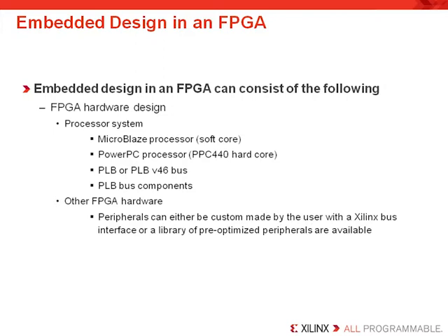Typical embedded systems are tuned for low cost, minimal power consumption, relative speed, and minimal FPGA resource utilization. As you may know, many customers like to store their software code inside of the FPGA block RAM. The caveat to this, however, is that there is a limited number of block RAMs inside of the FPGA. But this will depend on the device family and, of course, the density of FPGA you decide to purchase. Typically, most customers choose to use an off-chip memory for their application if they need a large amount of software, such is the case if they need an embedded RTOS.